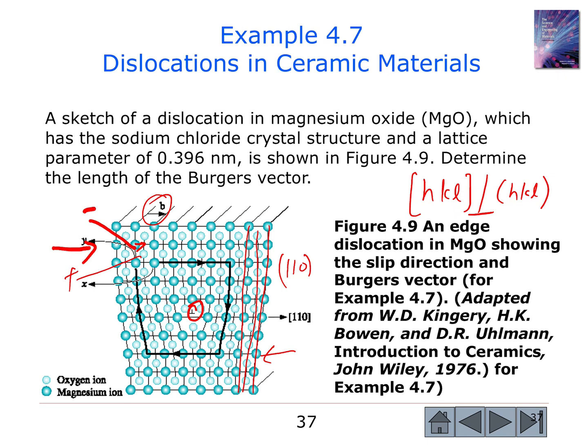Okay, and a negative will come near another negative ion and they will repel each other. So we are going to have a separation of the planes because of the repulsion between similar charge ions, right? So that's why the dislocation cannot be easily caused to move in a ceramic material. In certain planes it can easily move around, but not in many planes.